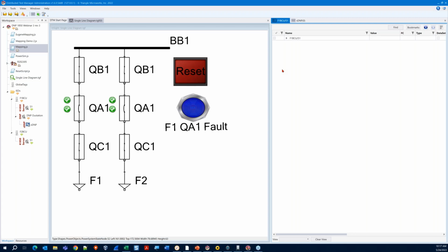What we saw in Christoph's last couple slides, setting up this demonstration, was the engineering process that you might use to configure the GOOSE communications which went between two devices. So we've taken that SCD, or System Configuration Description file, which Christoph set up using Helix, and we've imported it into our tool, Distributed Test Manager, where I've simulated both of those 61850 devices, seen here on the left.